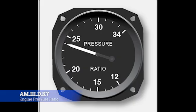N1 will generally replace it as the primary thrust indicator. It's sensitive to environmental conditions like altitude and temperature. So obviously, if it gets cold outside, the air gets more dense, or if you get really high, air is thinner. So this is all going to affect your pressure ratio.